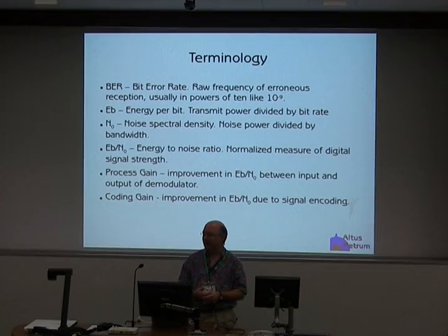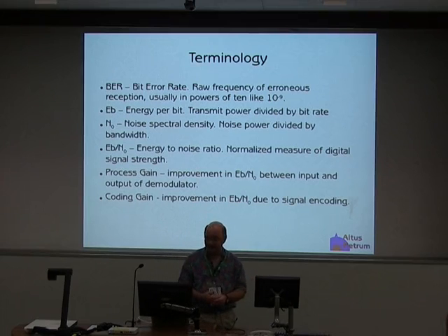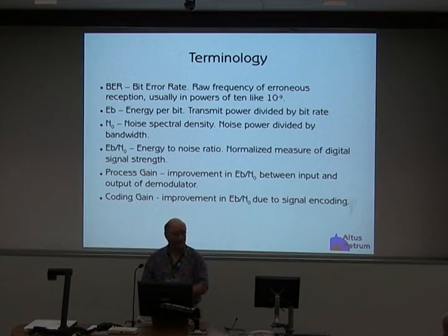And those are inherent in just the modulation scheme. There's no gain from additional transmitter power. There's no gain from fancy antennas. It's just you chose a smarter modulation scheme, you get to win. People who use things like on-off keying or AFSK, they get to lose because they chose a poor modulation scheme. So in this case, smart people get to win and use lower power transmitters and get longer range, like from